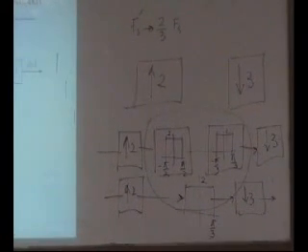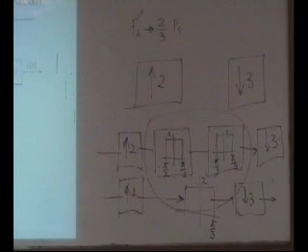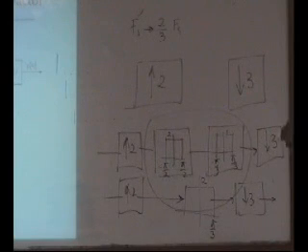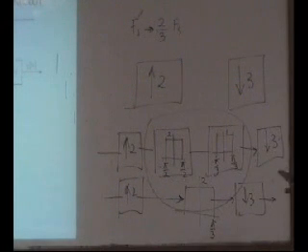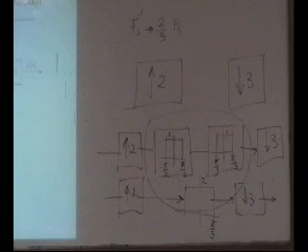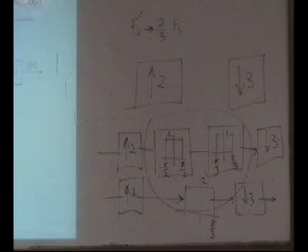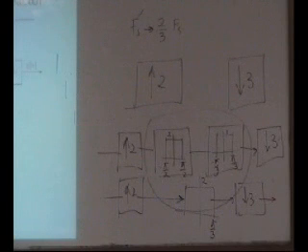I'm not sure if you can figure out an IIR filter for this as well. But this is where you first insert zeros, pass it through a filter, and then you throw away samples. Though I know there are polyphase decompositions for this as well, very complex polyphase decompositions, there is no straightforward way of doing it. This is if you intend to change the sampling rate by a non-integer factor, but it's a rational factor.